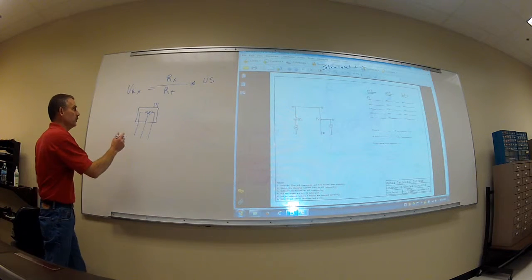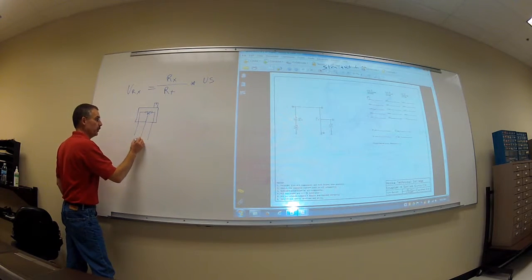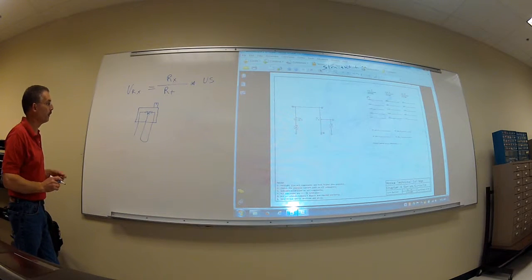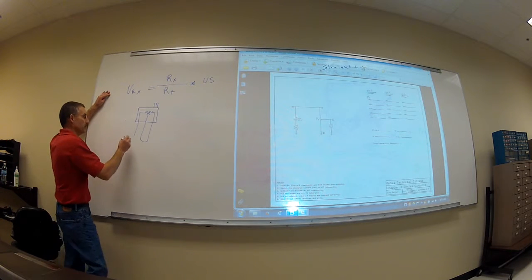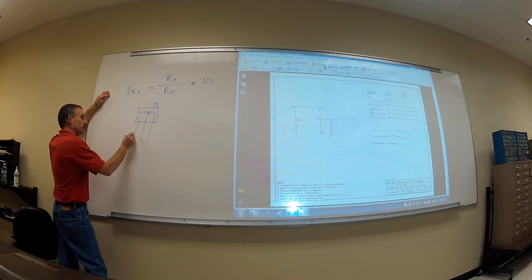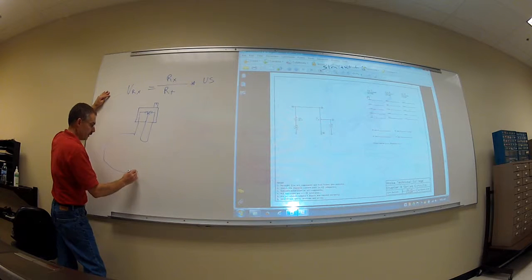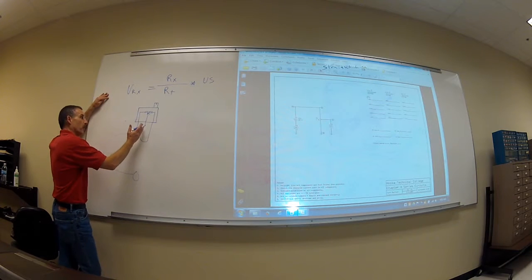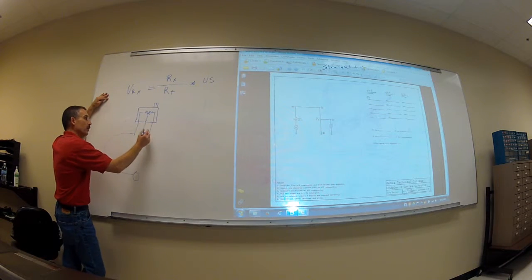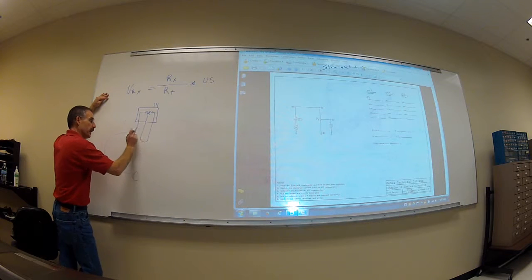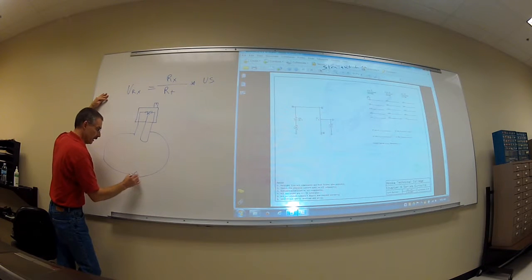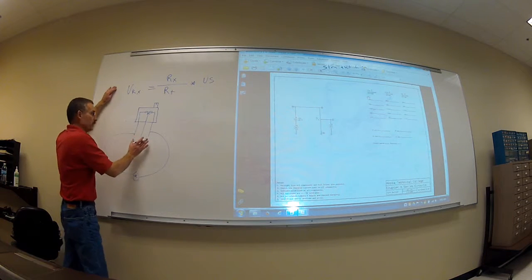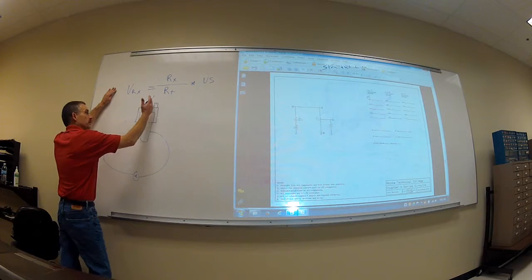Okay, now they've been jumpering these two leads. So we've been doing that in our proto board. When you're measuring your resistance, coming off with your ohm meter, you're coming out from one pin, and it doesn't matter now because since we have our middle wiper tied to our outer lead, we can tie it to either the middle wiper or this one. We got that piece of wire that's jumping in there, and so then that can come down to the other one. Okay. And that'll give you your measure of resistance as you turn your thing.